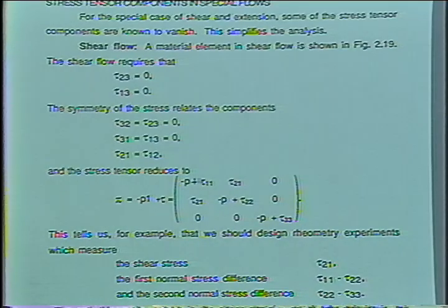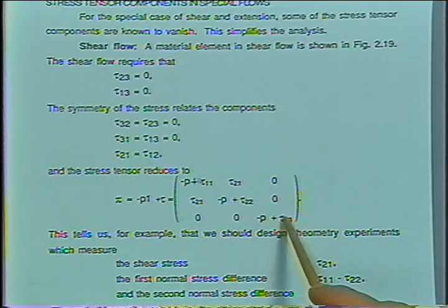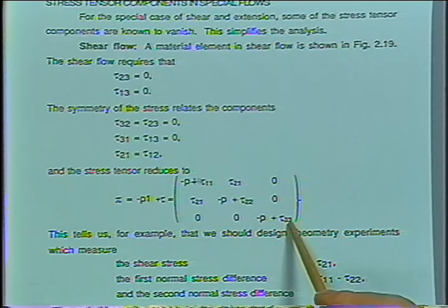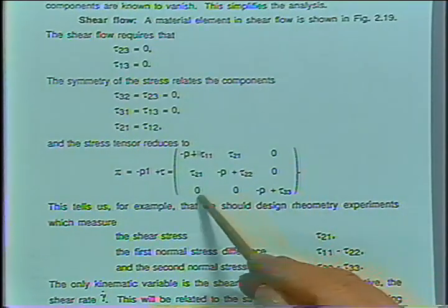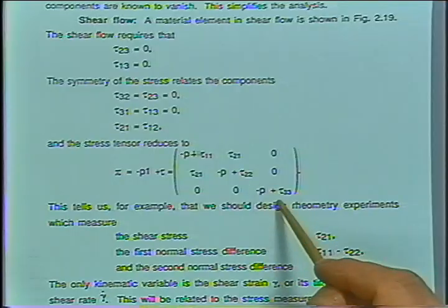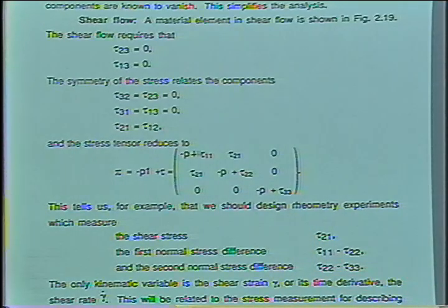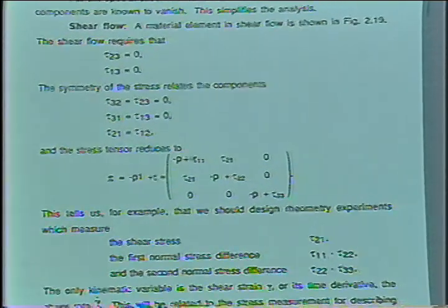We would have to describe it with some angle between the flow direction and the two direction. But certainly the third direction is a principal direction. So you can see those terms are 0 in the matrix, and 3 is a principal direction. It's a plane stress, which we are going to look at.